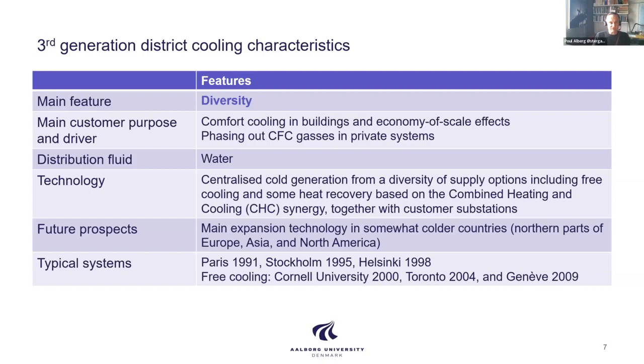and one of the things that was also a driver for this phase of district cooling is the phasing out of CFC gases in private systems. So you have all these ozone depletion refrigerants, and if you can take them out of hundreds or thousands of individual installations and have only one large installation, you can have a basically professional capability of maintaining these systems, and you wouldn't rely on hundreds or thousands of commercial or private owners to basically control their systems. You'll take all these CFC gases out of those systems and put them into some common systems. So here you would again simply be distributing cold water, which is fairly harmless in most cases.